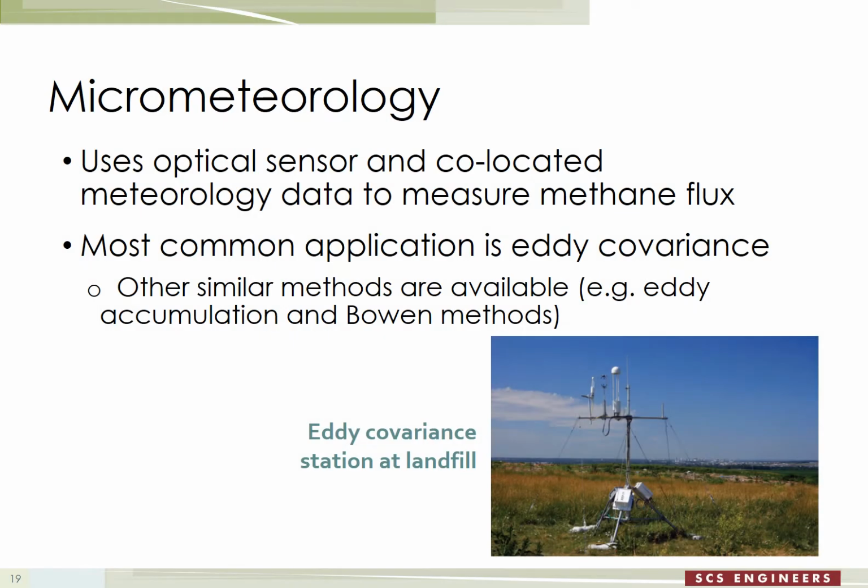Other methodologies are termed micrometeorology, and basically you're still using similar optical sensors, but these are placed at different heights above the surface of the landfill, and those are co-located with meteorological measurements, and multiple readings are taken over time at these different elevations above the surface, and ultimately used to develop a flux rate for the actual methane passing through the cover.